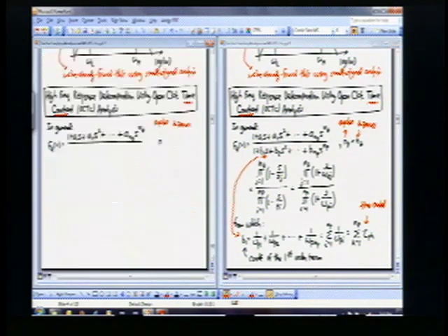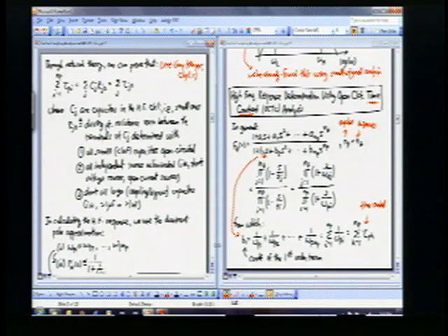Now, continuing with this, through network theory, and this is where Gray and Meyer does all this math that I'm not going to talk about here, you can get from this point, where these things are not necessarily related to this B1 here, but you can prove that the sum of all of these time constants from 1 to n sub p, where again n sub p is the total number of poles you have, is going to be equal to the sum of all the capacitors and this Rj naught, which is a driving point impedance, multiplied together.